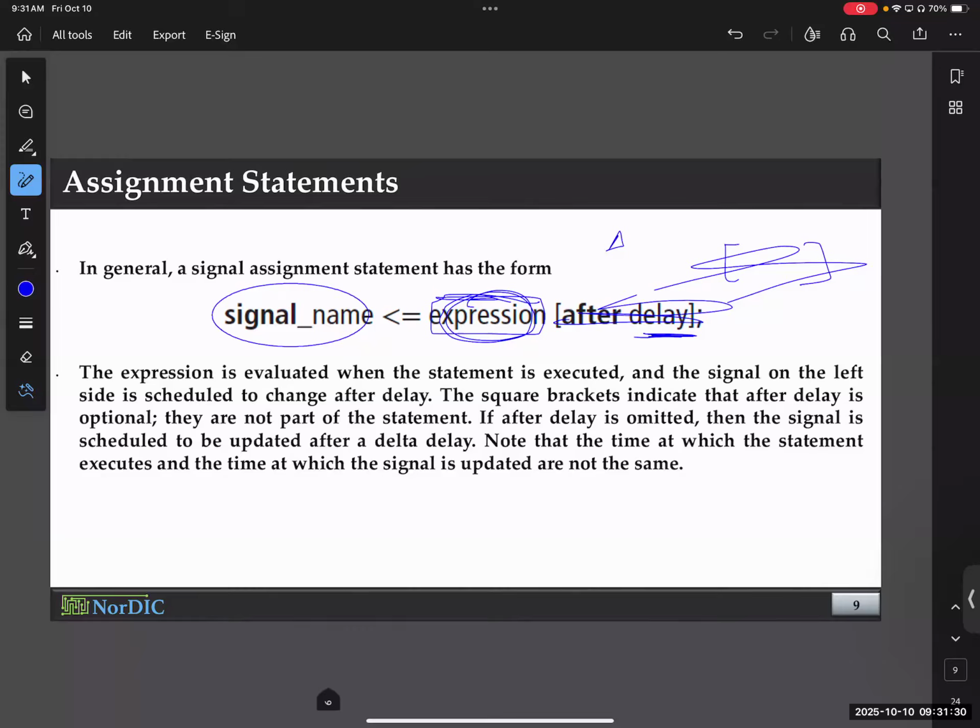There are standard cells that you can just call, and those standard cells have been characterized this way. They already have the delay in them. They have other parameters in them that were characterized by the engineers who were responsible for that. Does that make sense? Intel, NVIDIA, AMD, they all maintain their own standard characterization numbers. But if you don't mention anything, it will just take some random values.